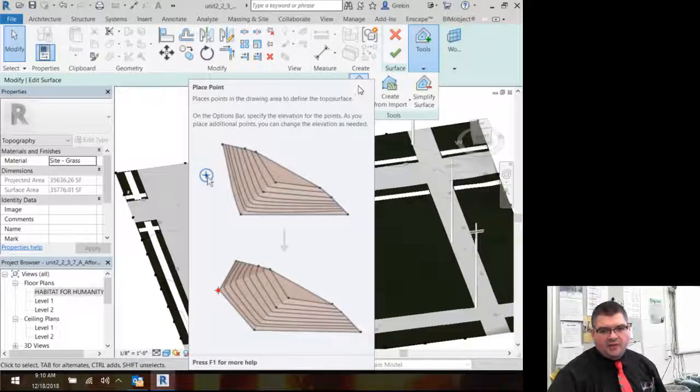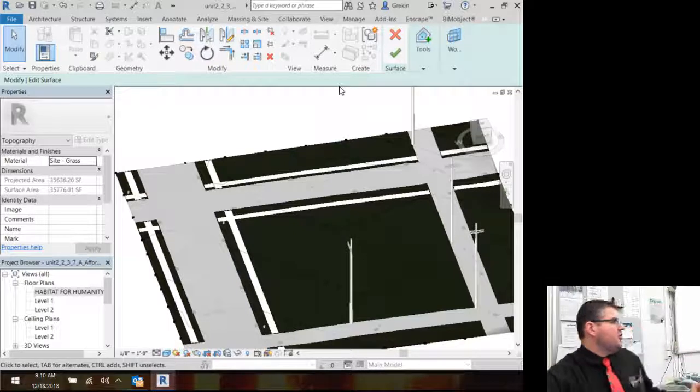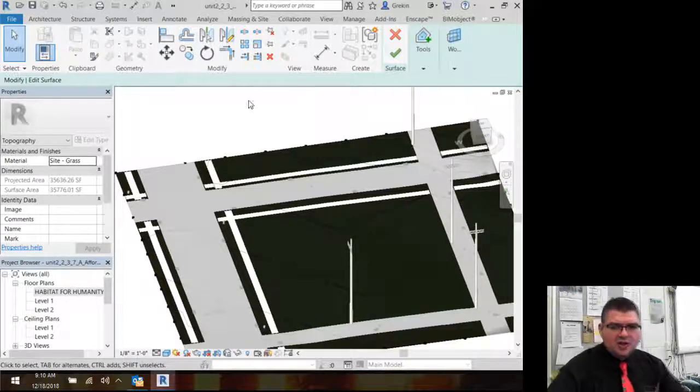All of our topography is made by clicking on points and telling the computer at what elevation that specific point is. And then the computer decides how it gets from that point to the other points that exist. In order to create a surface, we need a minimum of 3 points. It'll create the surface that those 3 points create, if that makes sense. Let's look at our other points first and see what height we have.